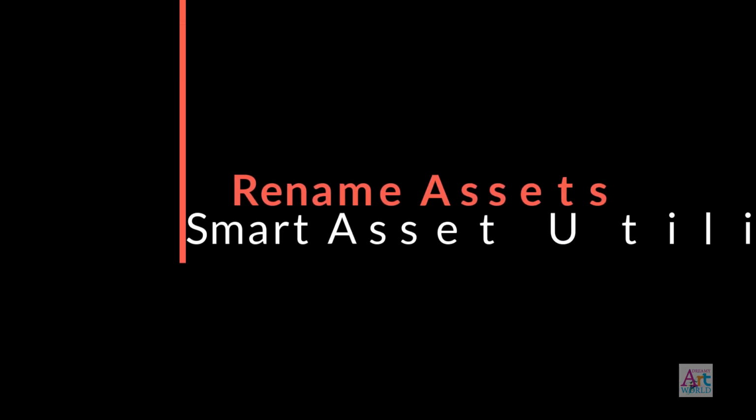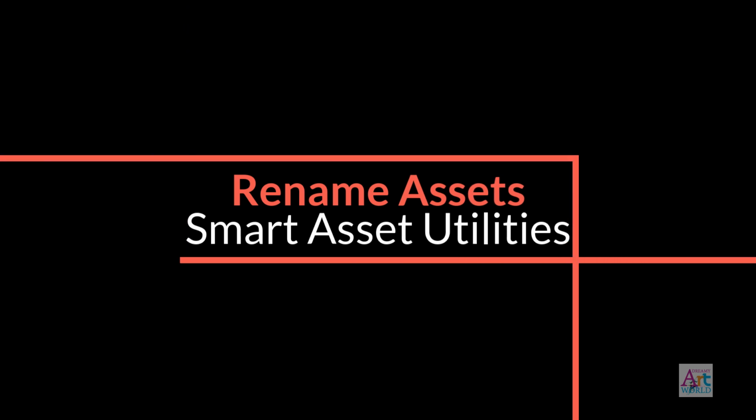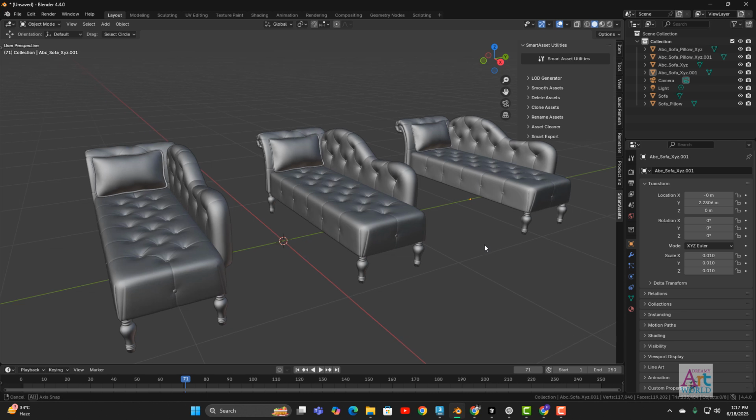In this section, let's take a look at how to use the Rename Assets tool from the Smart Asset Utilities add-on. It's a fast and flexible way to rename multiple objects in one go. First, select the objects you want to rename in your scene. Then open the Smart Asset Utilities tab and expand the Rename Assets section.